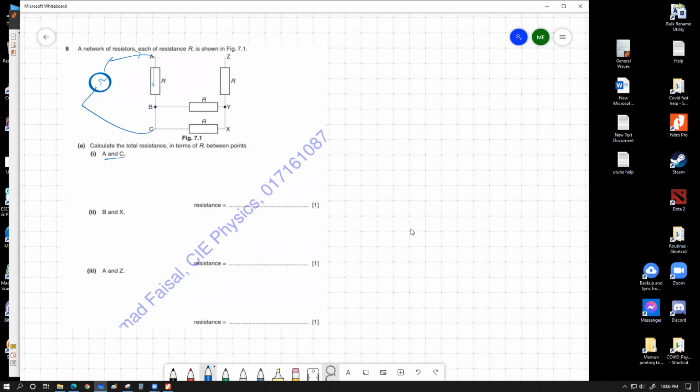Now you can see that from junction B to junction C, we have a single piece of wire, whereas we have another alternative path through two different wires over here. So this is a probable resistance path, and this is a zero resistance path. We know from our O levels that whenever there is a zero resistance path, that will take all the current, and within the resistance path there will be no current whatsoever. So even though there is a possible path, no current will flow through this pathway. All the current is simply going to flow through this path.